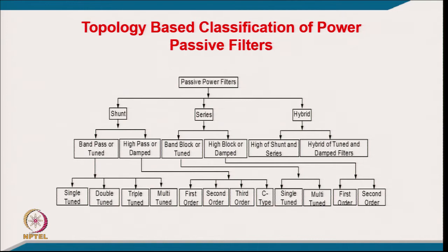They were not too popular earlier, because most of the converter load was current fed load, like the thyristor converter in HVDC that I have given as an example. Voltage fed loads started appearing only after self-commutating devices, when we have a voltage source inverter, and to derive a constant voltage source at low cost we usually use a diode rectifier with a capacitive filter, whether in power supplies, which we gave as an example in nonlinear loads, or in a small variable speed drive or an adjustable speed drive of medium power rating. Normally we use a diode rectifier with a capacitor filter, and that behaves like a voltage fed kind of load. So there the series passive filter is quite effective to block the harmonics flowing from supply to line.